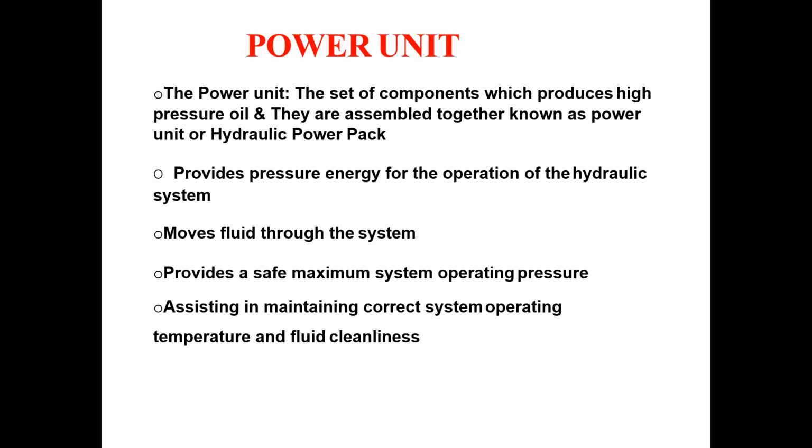So what is hydraulic power pack? It is a device or set of devices which is used to produce the high pressure oil, and we name this group as hydraulic power pack. Then what are the components of this hydraulic power pack? The components are accumulator, pump, reservoir, motor, and manifold for multi-connection, pressure gauges. The single name for all these components assembled at a single place is hydraulic power pack.